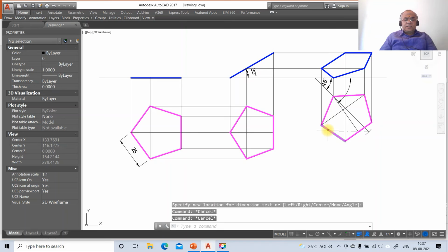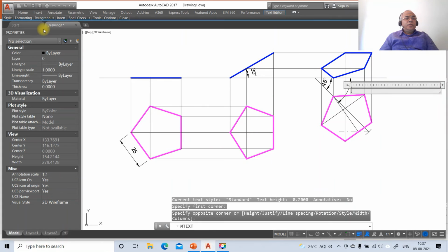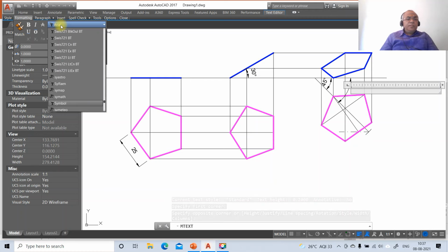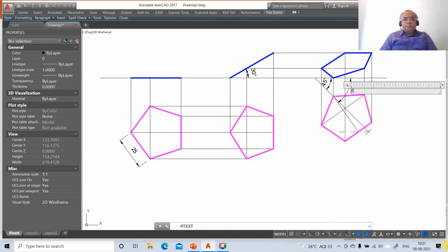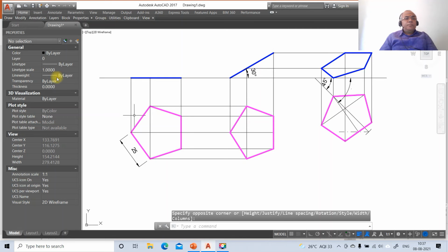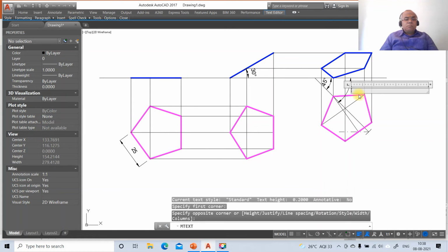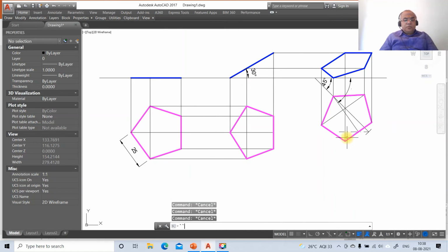Then go to M-text, select this window. Then you are going to get formatting. Go to symbol, select the symbol, and here you type beta B. Then OK. So here go to M-text, select this, go to M-text. Sorry, first we have to go for D-text.